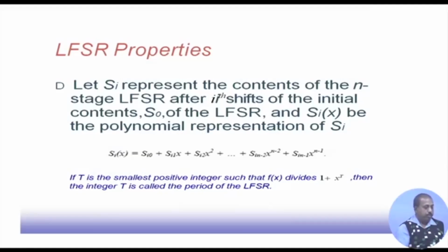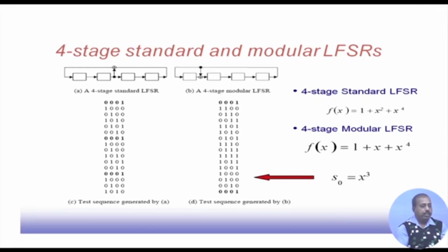It gives rise to many interesting properties, like say this one. Here, if we count this standard LFSR as 1, x square, x cube, x to the power 4, then you see that while doing this addition, we are taking the terms like this 1, which is definitely there, plus this x square term and x to the power 4 term.